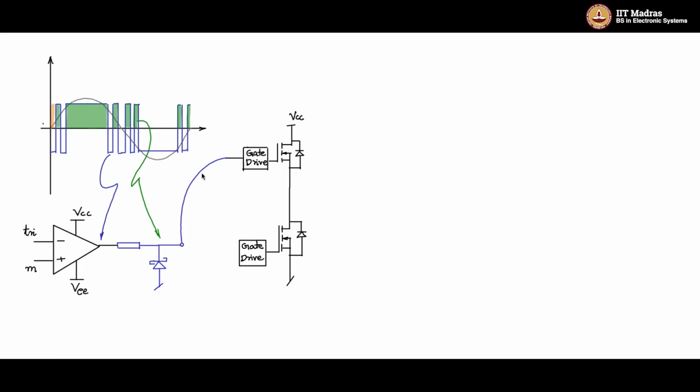Now this gate drive circuit, I am going to connect directly to this part, the green part. And what do you want to connect here? This MOSFET should come on during mutually exclusive intervals of time. During the time when the top MOSFET is off, you want the bottom MOSFET on, that is, during all these blank zones or inverted portions, you will see the bottom MOSFET coming on.